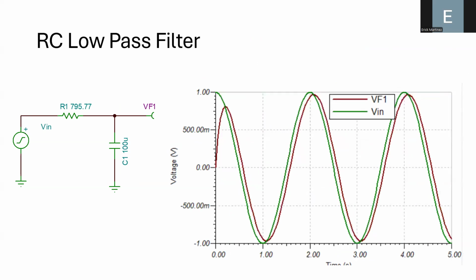And here I place an input cosine function that has a frequency lower than 2. You can see here that the amplitude stays mostly the same if you compare the input and the output voltage. You also need to be very careful when you're filtering, because you can reduce the amplitude of your signal, so you are in a sense losing some information. That is why you need to design your filter very effectively in order to avoid this information loss.